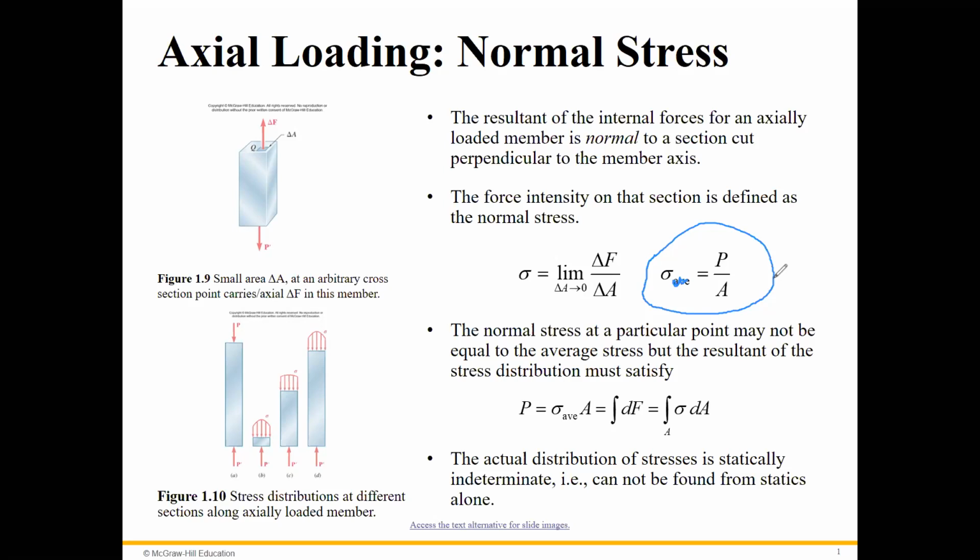Decrease the area, or actually increase the area, no? Increase the area, exactly, the cross section area, right? For example, we find P from statics. Then we have maybe a cross section of 2 by 2, and the stress is greater than allowable. Then this is not good, so we need to pick a stronger or larger cross section.